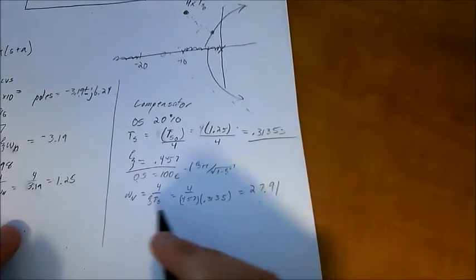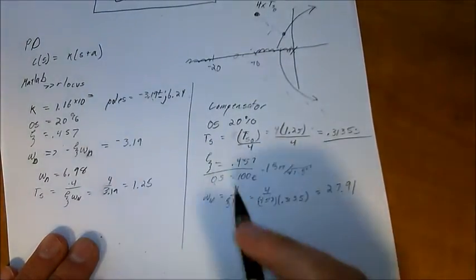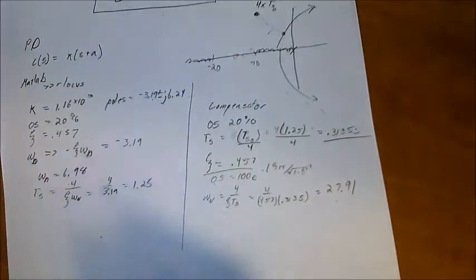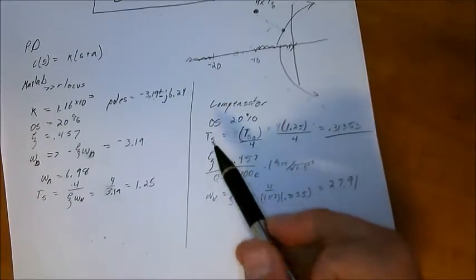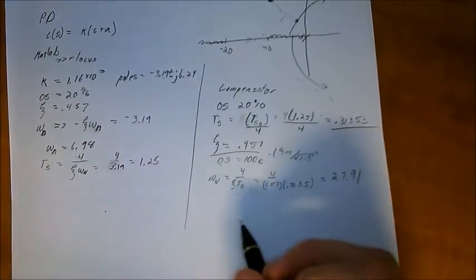So you can do this calculation, but really it's just easier. Omega n, the natural frequency, is going to be 4 times what it was back here because we're compressing it basically by having a faster Ts. So this is 4 times omega n.